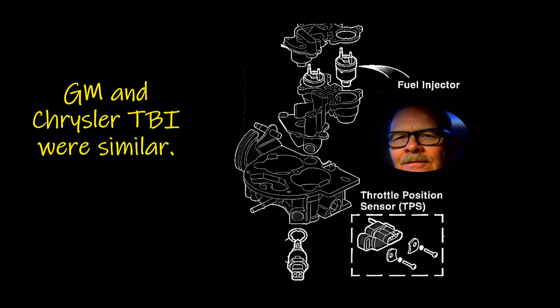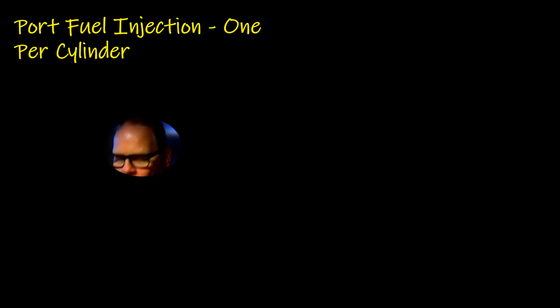On the other hand, those central sequential fuel injection systems with the little poppets and the spider under there are supposed to have like 61 pounds of fuel pressure, and if they've got 58 pounds of fuel pressure, they may not even start because of the way those poppets are set up. That's another whole other story. I can do some more on that.